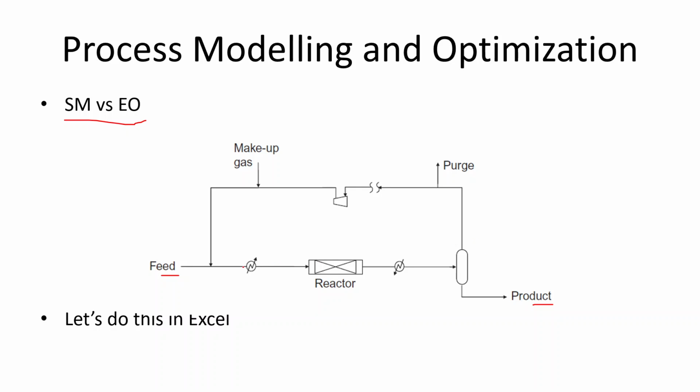And then we may have some impurities either from the gas makeup or in the feed, whichever they're coming from, and that unwanted material, maybe inerts or maybe produced in the reactor. Nonetheless, if they are accumulated here, we have to get rid of them.